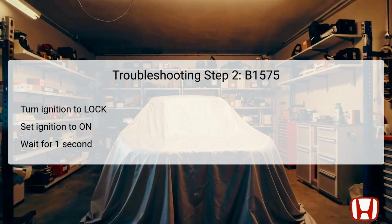Following the initial troubleshooting step, the next action is to turn the ignition switch to the lock position and then back to the on position. This procedure is vital in reinitializing the vehicle's electronic control systems for a more accurate diagnostic process.